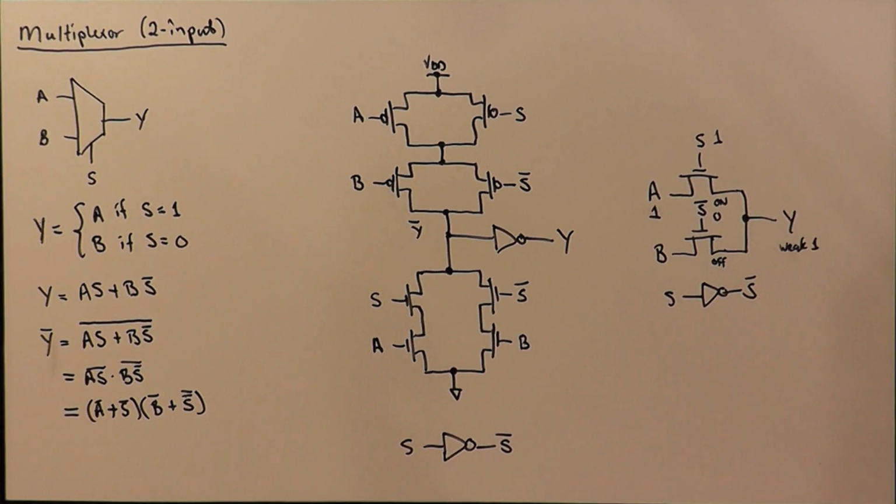We would say that Y would be about a threshold voltage below VDD, but as it turns out, that threshold voltage, because of an effect called the body effect, isn't going to be like 4.7, or rather 4.3 if the threshold voltage is like 0.7. It's going to be more like 3.5. And that's really not super good,